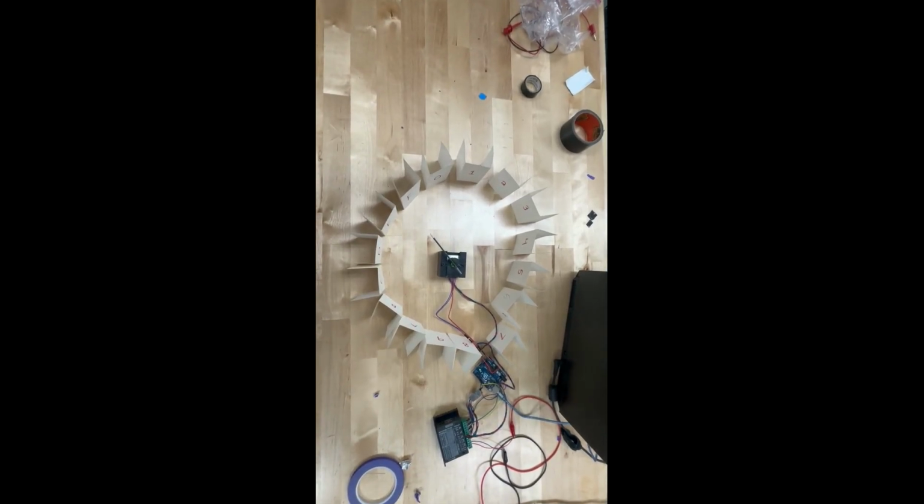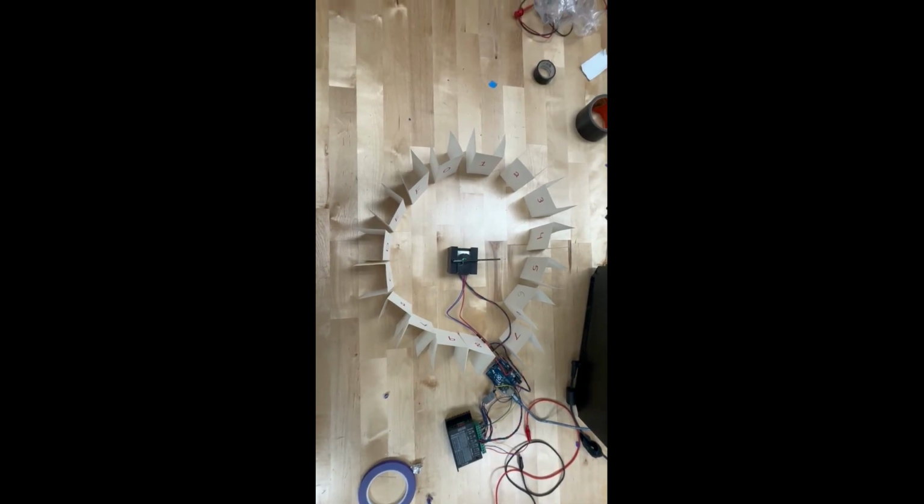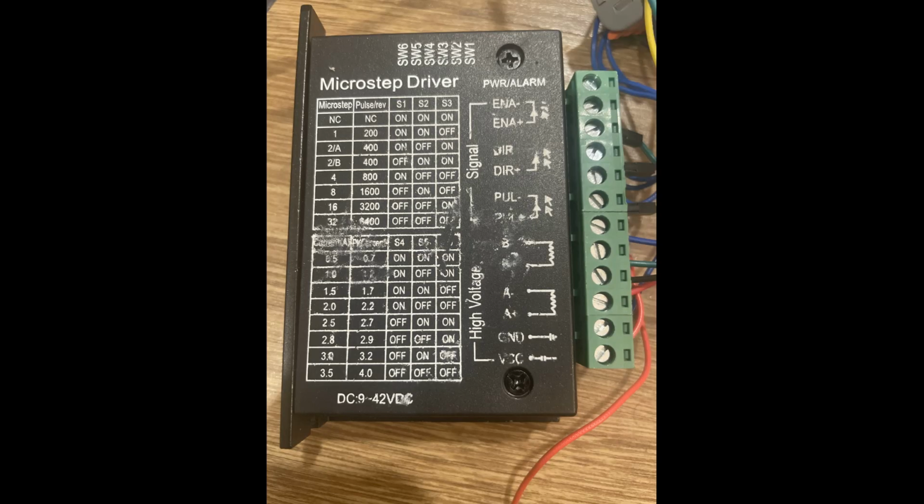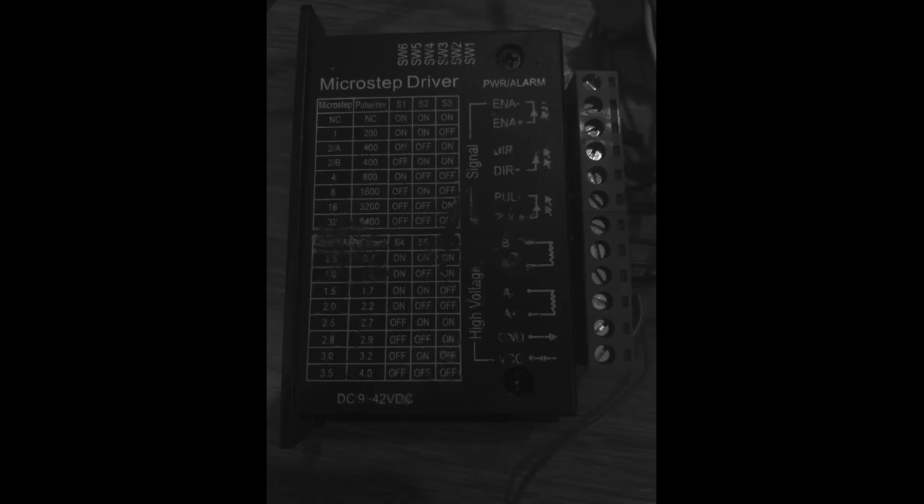As this happens, more current is supplied to the next coil pair, which raises the field strength of those coils. This advances the core again a small distance. These small distance increments are called steps. In the code we wrote, we can tell the motor to take a defined number of steps with the help of a control board, rather than having to directly control the power supplied.